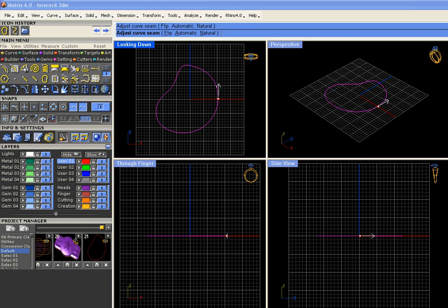So as you approach the other side of this white arrow, actually either side of the white arrow, you'll see its little counterpart, this little red arrow appear. When you see that red arrow, click it, and the white arrow will be reversed. Now move your cursor away because you don't need to change it again, and the other arrow pointing the other direction will disappear. Again, just to show you that process, when you have the incorrect arrow going in the counterclockwise direction, simply approach it with the cursor. When you see the correct arrow appear, left click once, and the white arrow will be switched. You'll still see the other arrow, but just simply move away from it with your cursor, back away slowly, and you'll see only the correct arrow remaining. Now press enter to keep your changes.